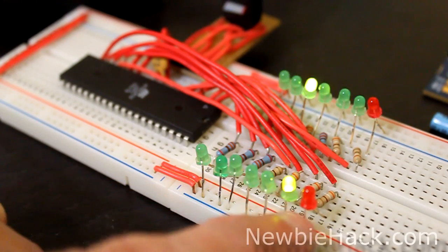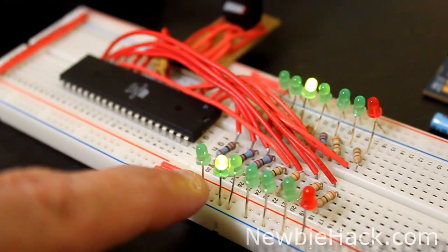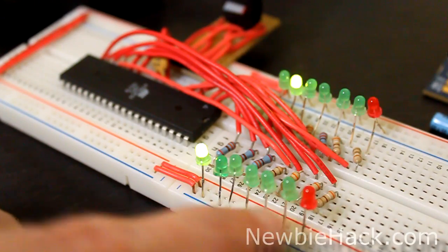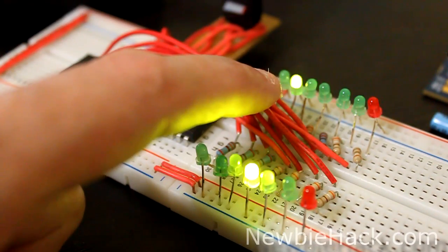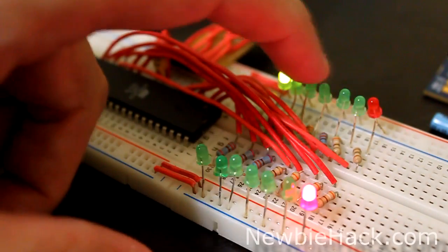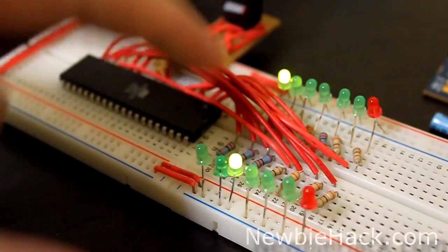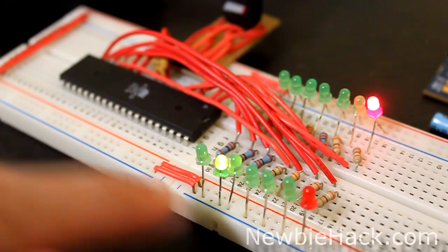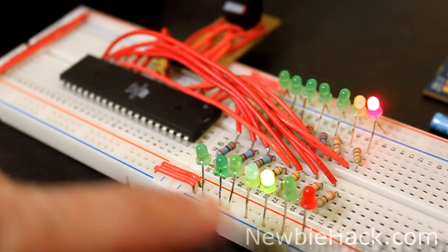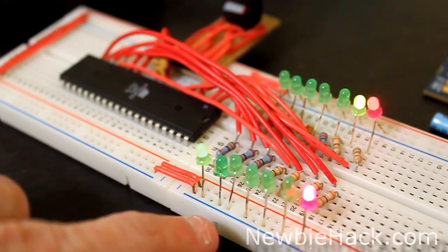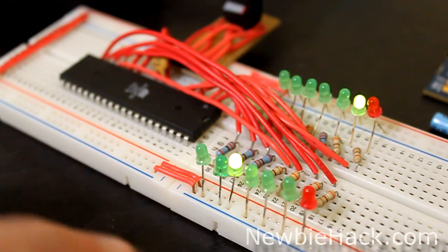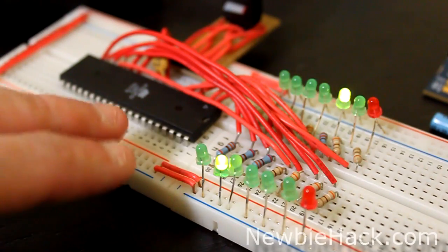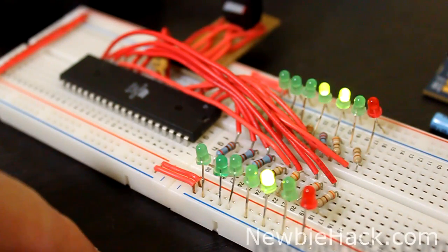You can see that this is just toggling from one LED to another, and it is going from one LED to another every second. And this one is every 1/7 of a second. You remember we had 7 of these LEDs, and it'll just chase from one to the other, and then this one will change. This is all going according to the internal clock, which is actually asynchronous to the core of the CPU. So those two processes can run simultaneously and not really bother the actual core of the CPU.